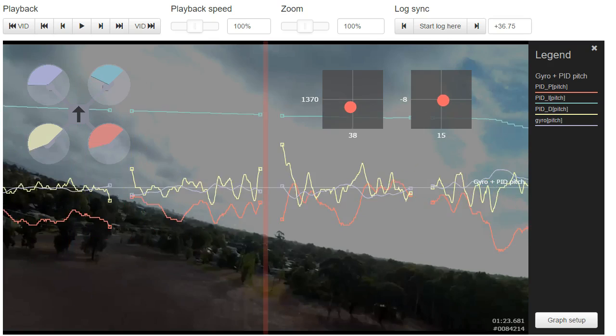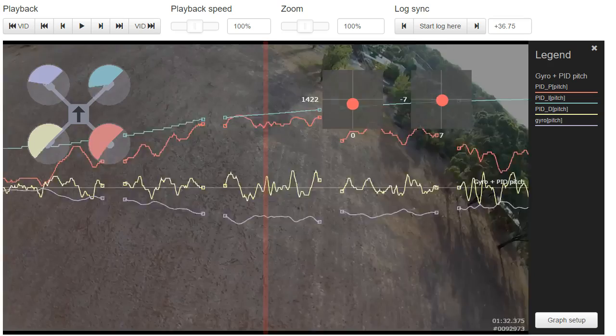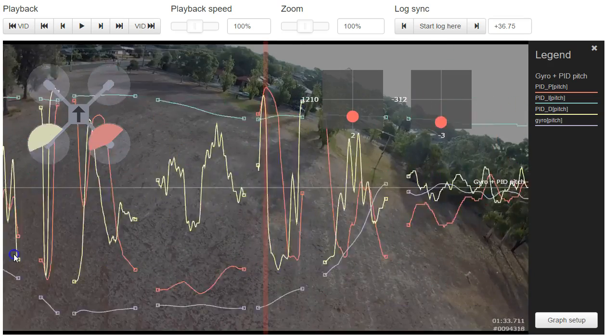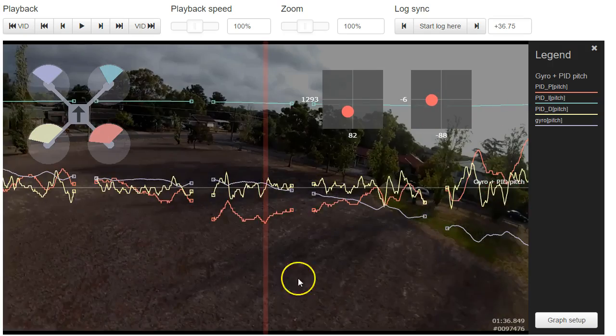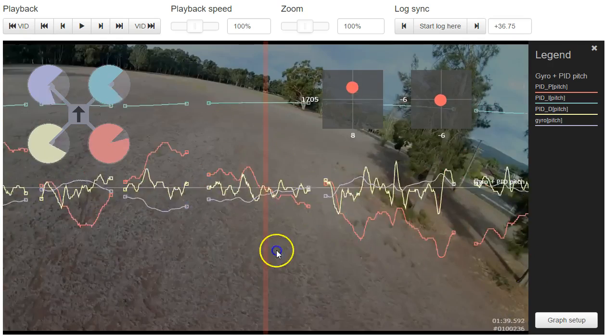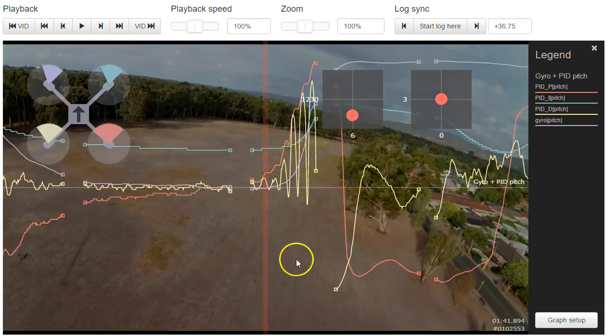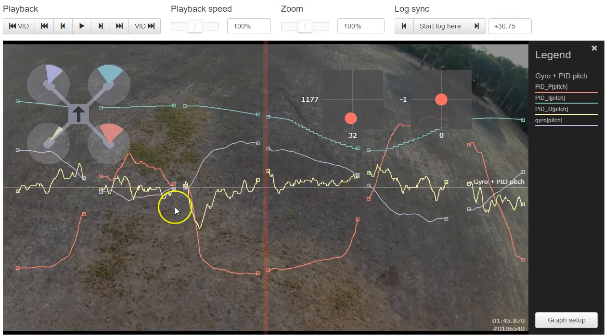I don't see any sort of signs that you're beginning to get into an oscillation scenario. I don't even see any of the surging that I've pointed out in previous videos. Barely starting to see some peaks here. So I think your P gain needs to come up to start with. I think your P gain can come up 1.0.